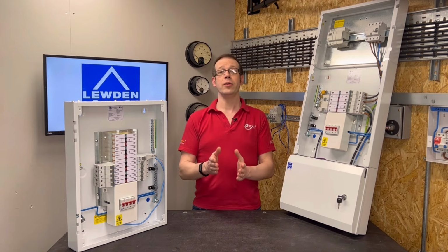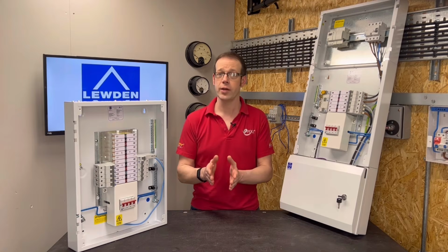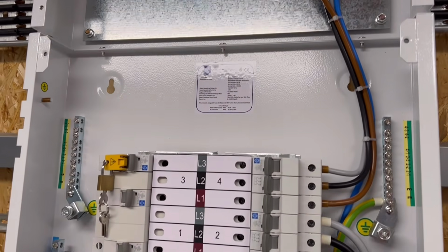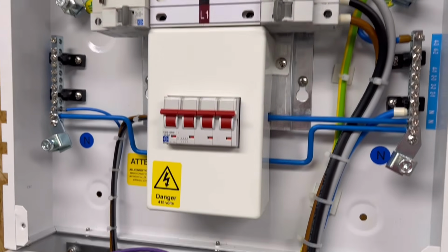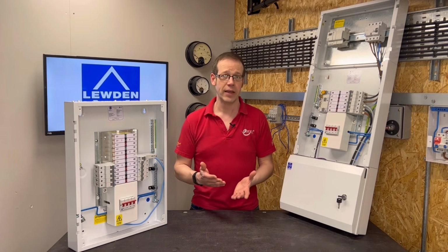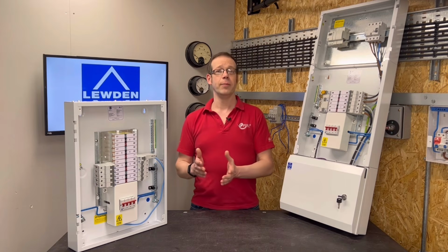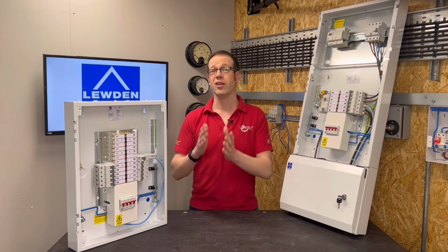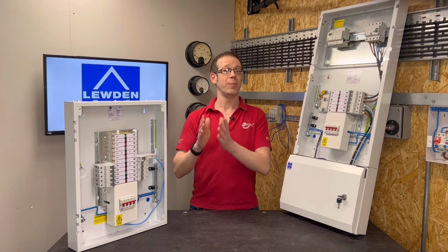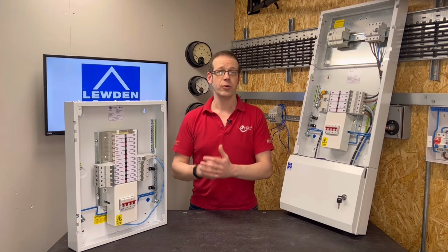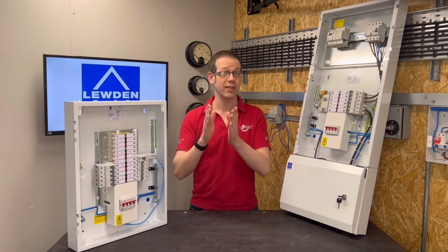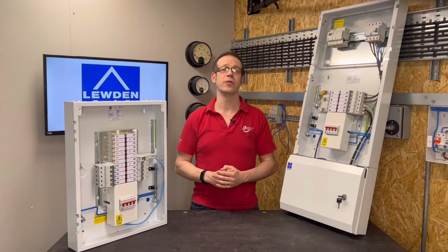And not only did the UK push for harmonisation in fixed wiring, they also suggested the colours that we now use for three-phase, as most European countries were using a mishmash of brown and black that were often interchangeable with each other. Simply using the red, yellow and blue that had been used in the UK for a long time wasn't an option for harmonisation, as Germany and Austria had been using red for a protective conductor and yellow was being used for the same purpose in Italy. You can readily imagine the dangers of swapping those colours to line conductors in those countries.